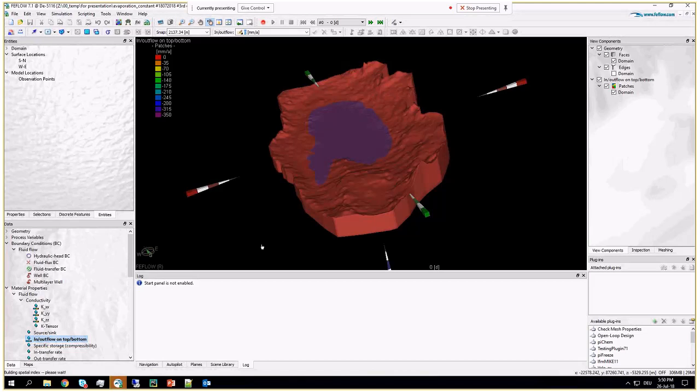And why do I do it like this? Because this is also a problem of mass transport. Maybe we also want to simulate density-dependent processes here. So it's unrealistic and also impractical to achieve a steady state solution for a very nonlinear system, which is Richards' equation here, because we solve unsaturated flow, and on top of that, we put more nonlinearity with the density term. So basically, you cannot identify appropriate steady state solutions.